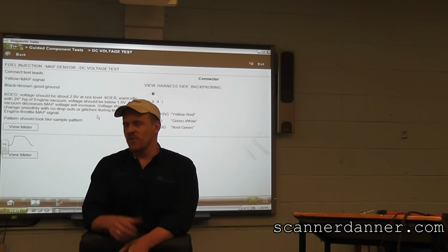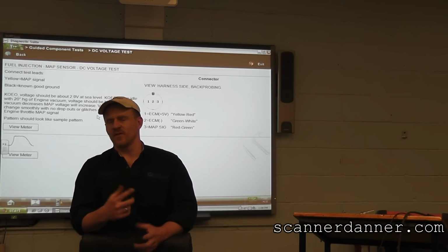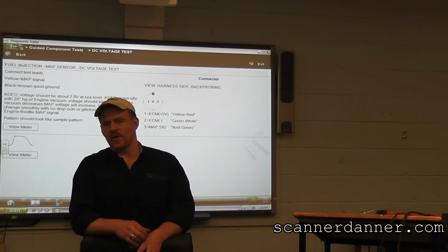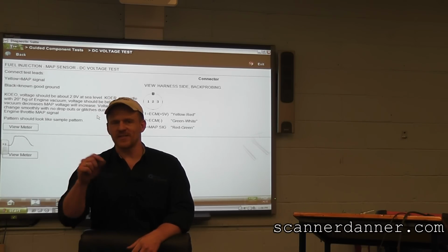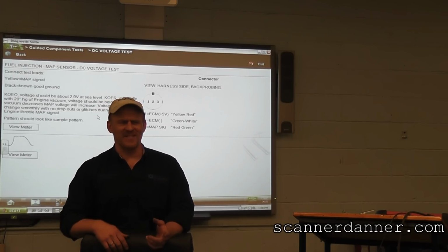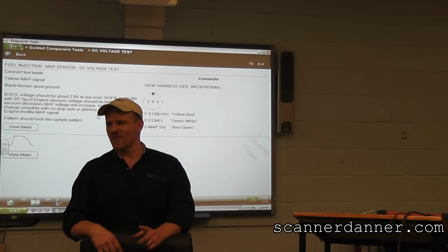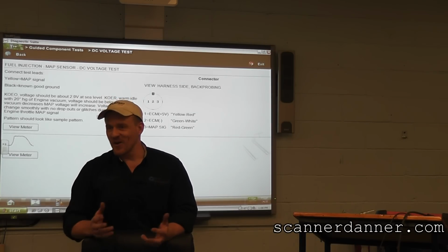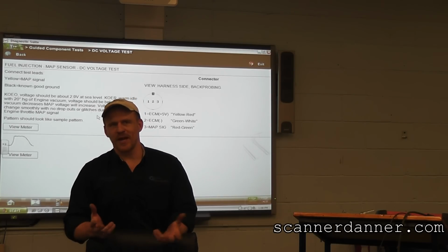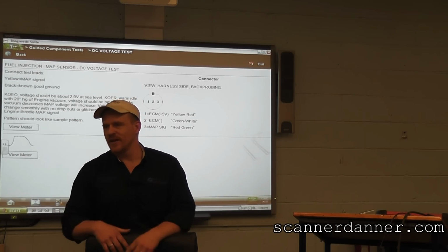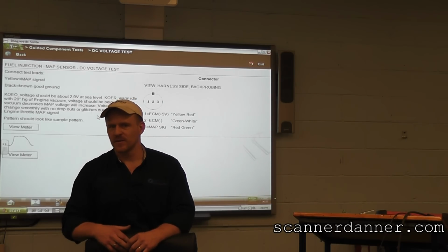If you were working in the field, you could probably have found this problem within 10 minutes of looking at it. As soon as we did our basic checklist, we would have been like, dude, why is that MAP signal changing whenever I open the TPS, open the throttle? So that's pretty cool. Put 2 and 2 together, engine was just swapped, and nice and easy fix.